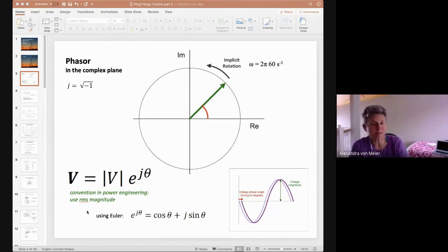And this is something that's totally not obvious if you're not into AC power, which is that even though the voltage is synchronous all across a connected AC grid, there's actually a slight change in the timing, in the phase, that's related to power being transferred from one location to another.